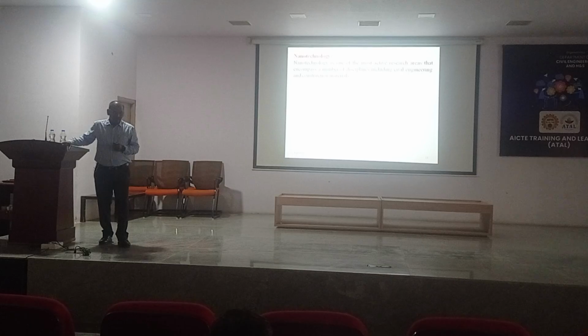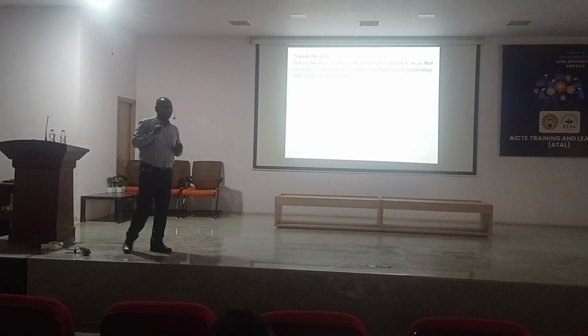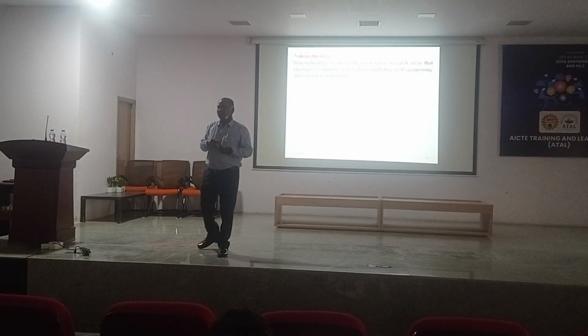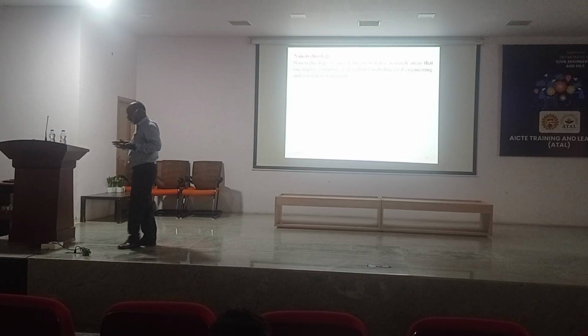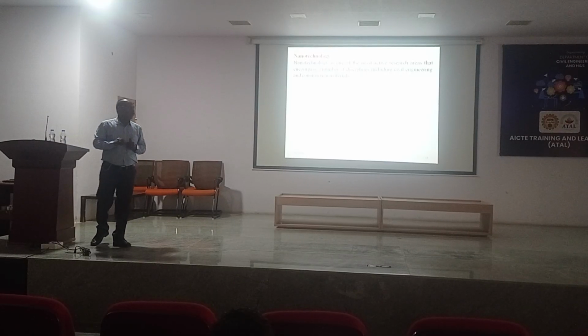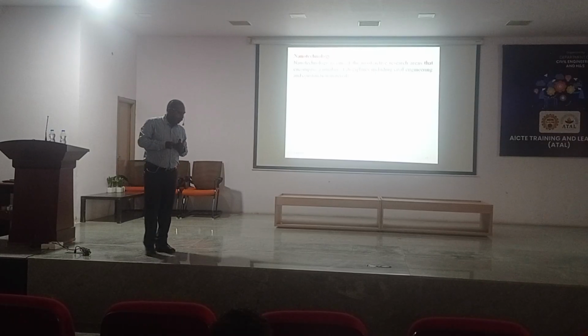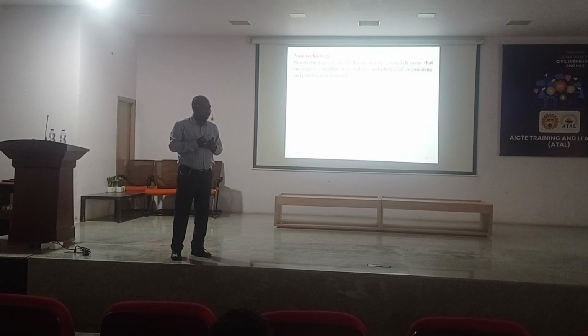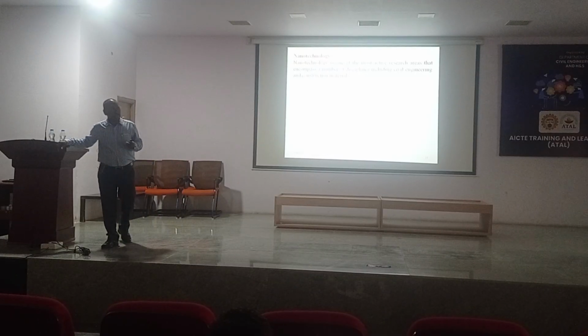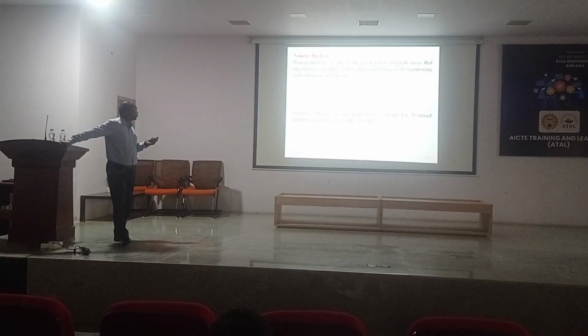One is dispersion. If nanomaterials are not dispersed properly, then there is no use of adding nanomaterials. Dispersion is very important. That means it can easily mix into the cementitious materials. That is one disadvantage, which we have to take care of first. And the next thing is, once you add nanomaterials, workability may decrease. More amount of water is required to increase the workability. These are the two problems everyone should take care of while using these nanomaterials.